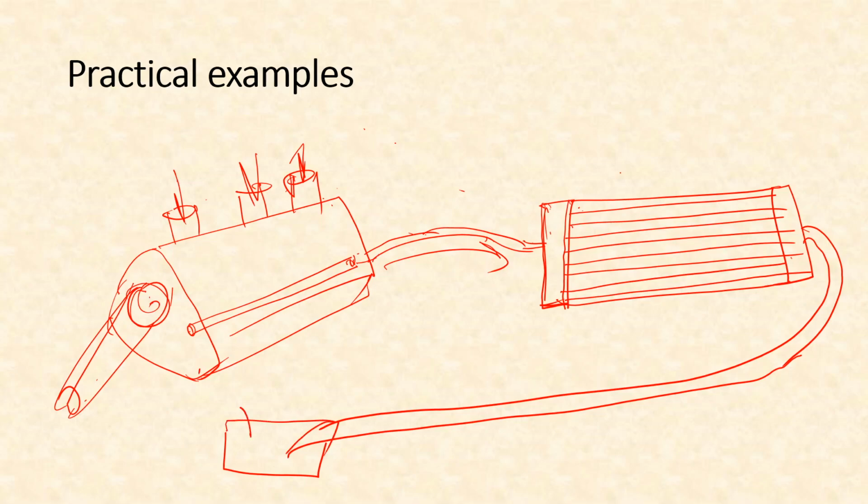Then this water is again carried back to a reservoir, so from this reservoir, again using a pump, the water is again pushed through this engine block. What happens in this radiator is that the surface area of all these tubes will, because there are a large number of tubes, the water flowing through these small tubes will transfer the heat.